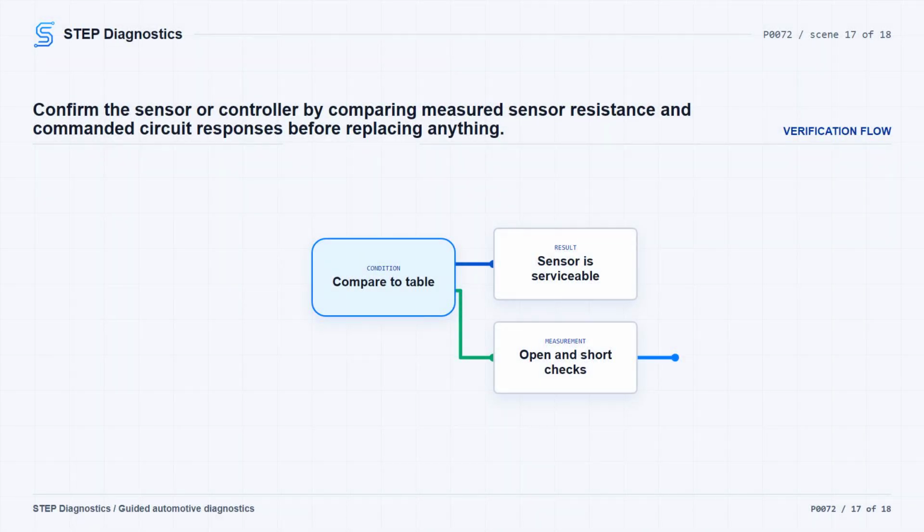If the actual ambient temperature can be measured or reasonably estimated, measure resistance across the sensor terminals and compare it to the table. If the measured resistance from the ambient air temperature sensor does not meet the values, the ambient air temperature sensor is individually serviceable. Do not turn that into a whole mirror assembly repair.